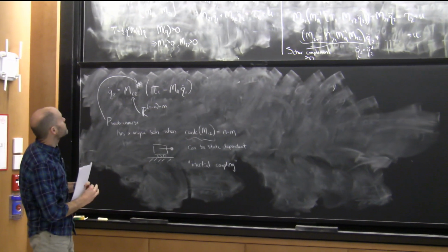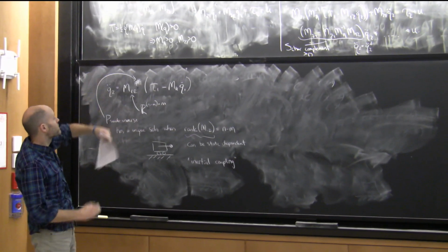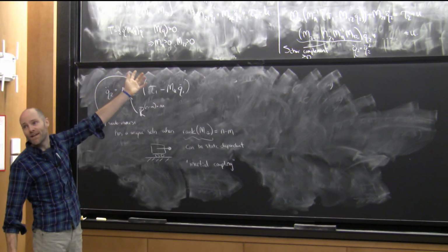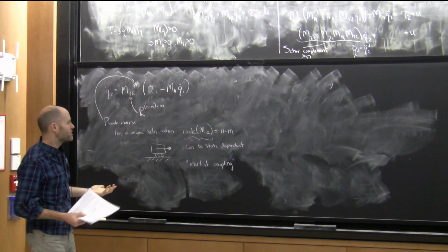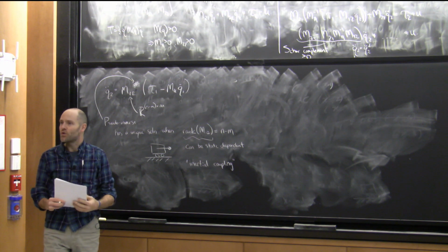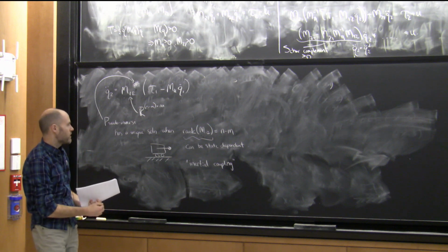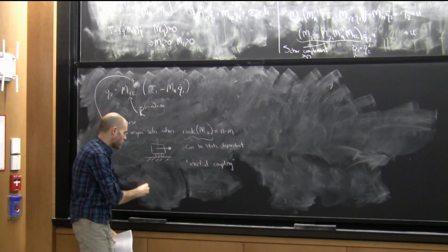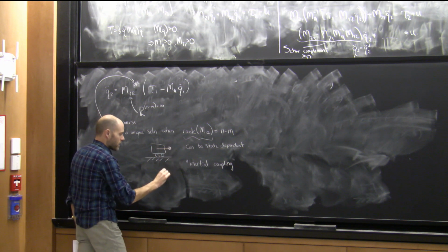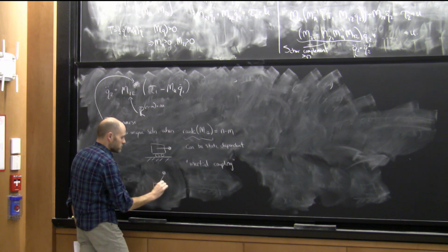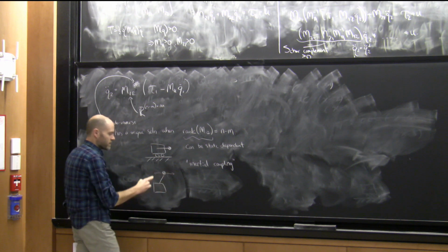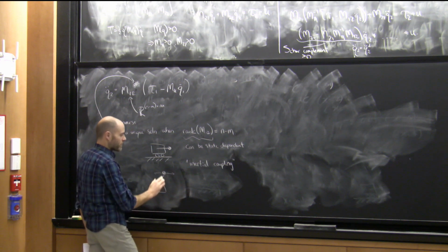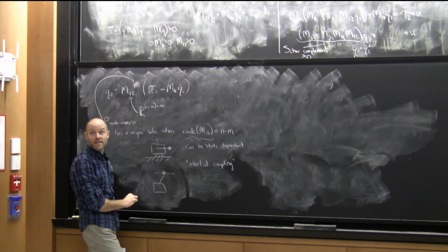So, this felt kind of arbitrary, right? Why would I just happen to want to control my passive degrees of freedom only and not my actuated? It seems like in general you should be able to pick any m things to control. Okay, so for instance, there's not that many options here on the cart-pole, but I could, for instance, care about, let's say, the x position of the pole. Let's say the variable of interest is somehow the position of that in space, and I could write a controller that's doing whatever it does to make that stay in some position.